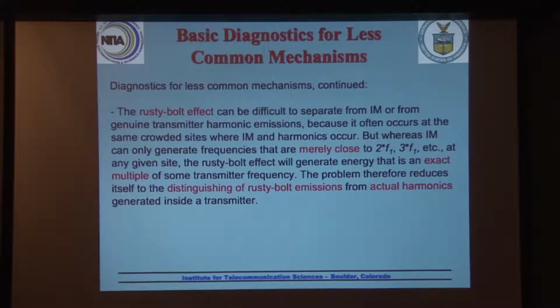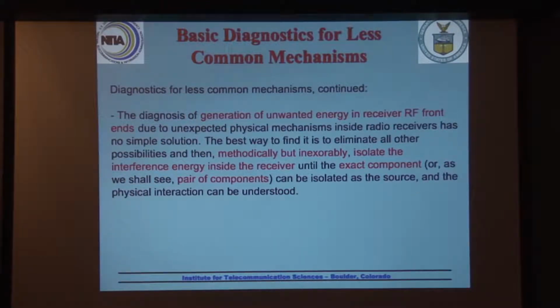So just bear in mind that if you see a harmonic, you have to figure out whether it's an intermod, whether it's coming directly out of the transmitter, or whether it's due to a rusty bolt effect. I will say that after 30 years of having worked on this kind of thing off and on, I've seen one genuine rusty bolt case. But there was one, so they do happen.